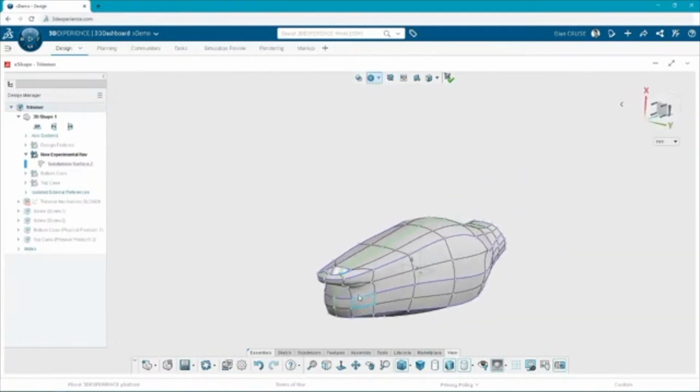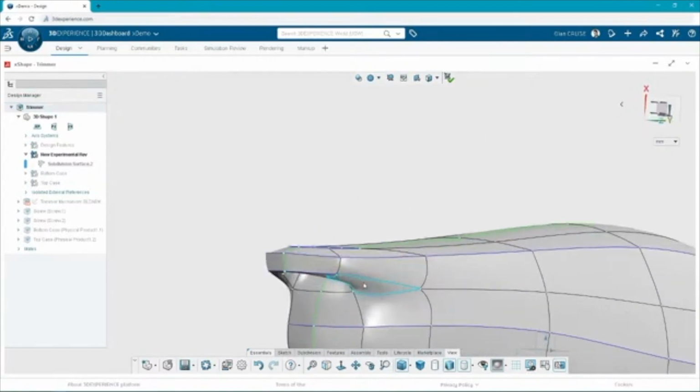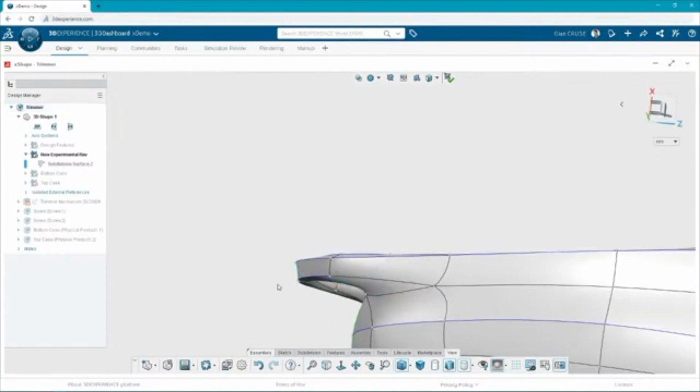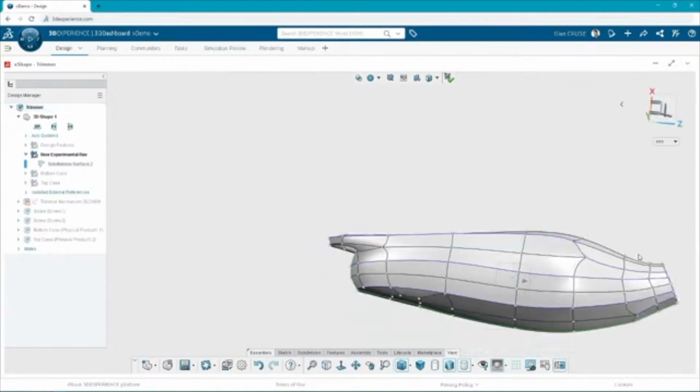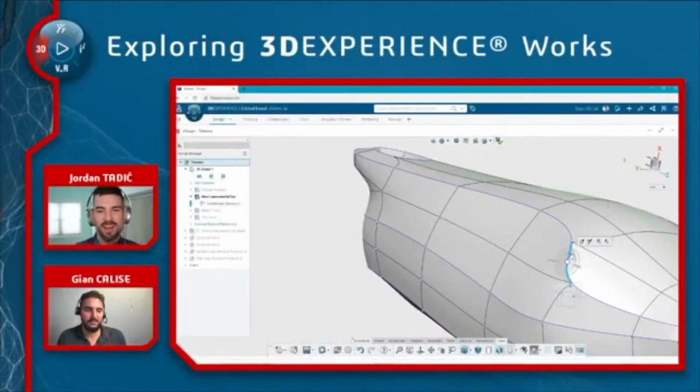Yeah. Yeah, straight curves and loops through there just lead to really predictable geometry. Yeah. When we're getting into draft analysis and things like that, much more predictable results and controllable results there to ensure it all looks good. And that edge you have selected right there, I was kind of on the fence with that one. Yeah, I don't love it. It kind of twists down through the model.